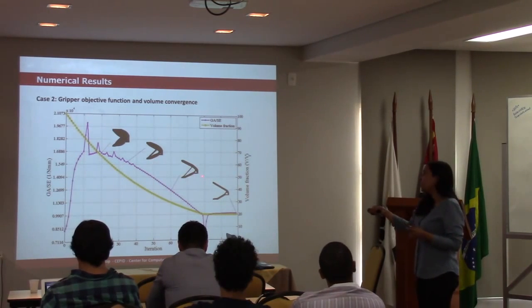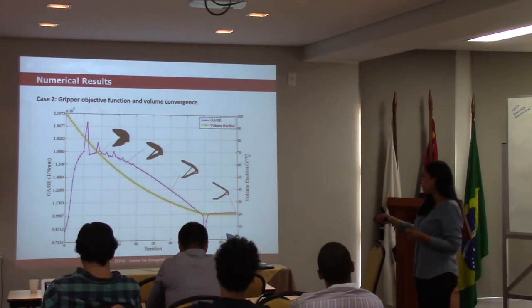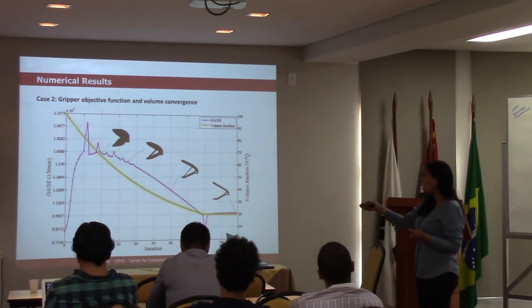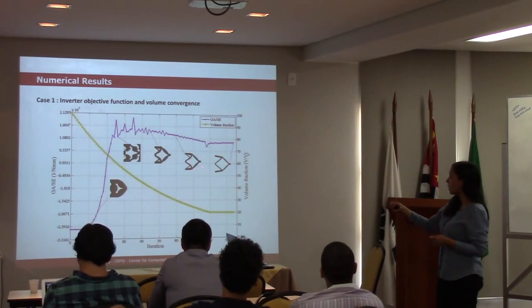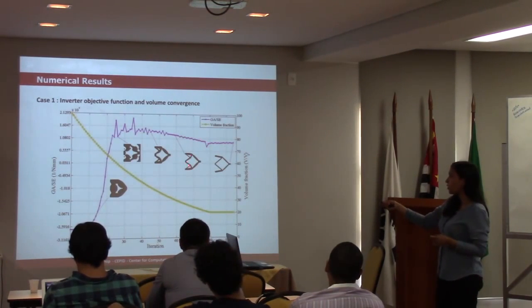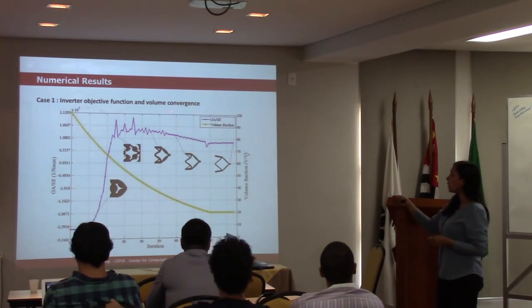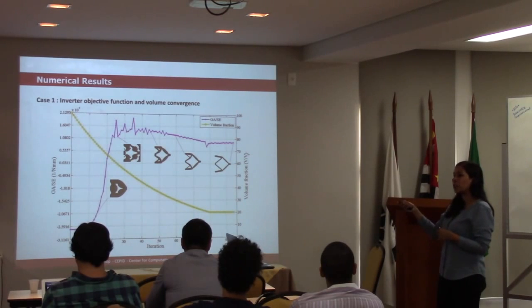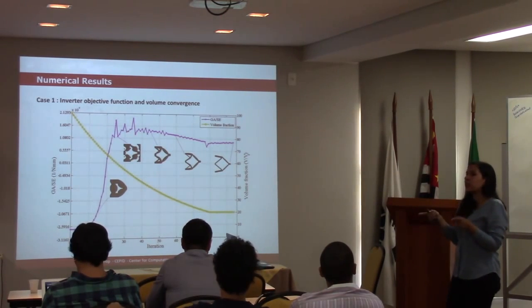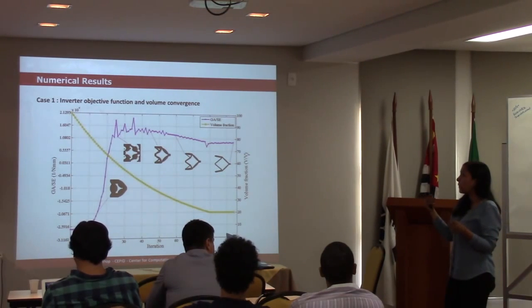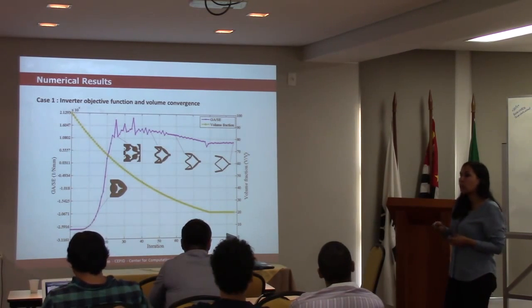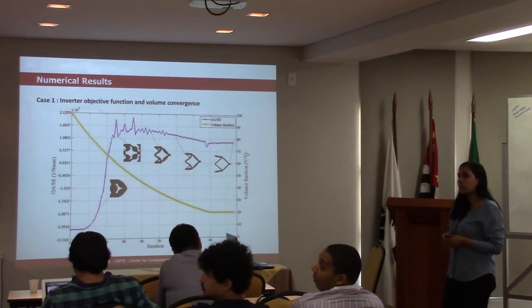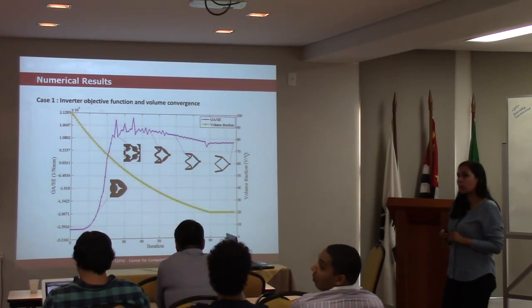And to do that, it needs to get rid of this bar. This is that significant change. If it did it only through here, it would do this. It's the same here, if you see, these bars. All of these are significant changes in the topology. From one iteration to another, the topology changed so radically that, for example, the compliance will be totally different, so the objective function changes also. At the end, the program can stabilize the structure without that part.